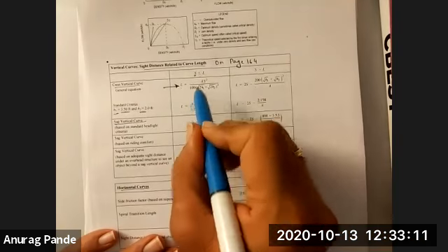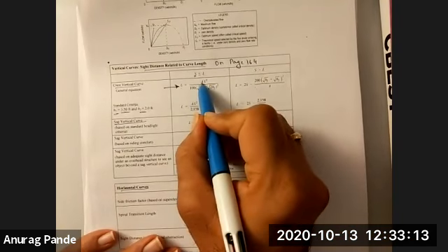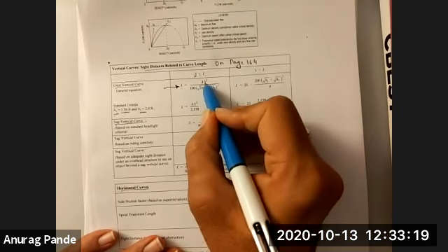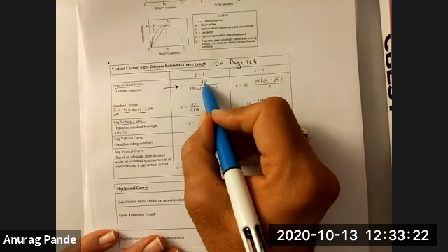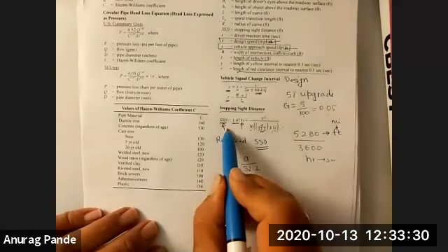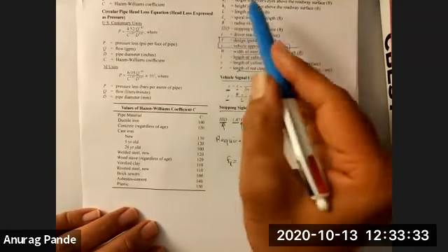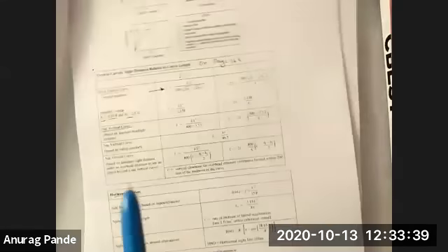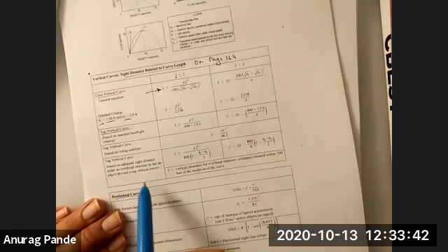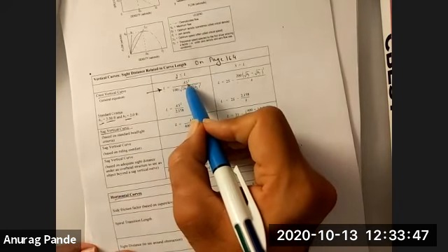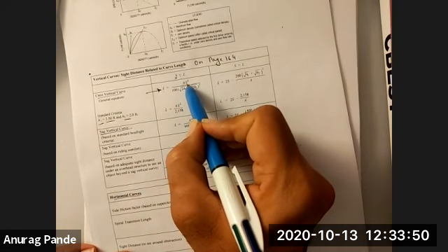And if S is less than L, I already defined the capital A value. That's the percentage change in grade, the absolute value of that. And this S is the stopping sight distance. Now, how do you find this S? This S will be based on the design value, and you will get that S value using this formula. I don't recall that they define S here, but the S value is essentially the stopping sight distance that you need to be able to stop on that curve.